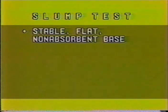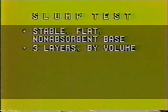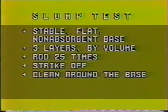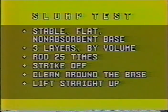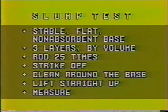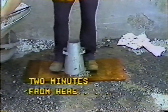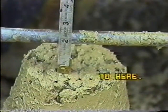And that's the slump test. On a stable, flat, non-absorbent base, fill the cone in 3 layers by volume, not by height. Rod each layer 25 times, spiraling toward the center. Strike off the top layer. Clean around the base of the cone. Lift the cone straight up without twisting or tilting it, and measure from the bottom of the rod to the top of the concrete, directly above the center of the base of the concrete. There's a time limit too. 2.5 minutes between the point where he starts filling the cone to when he measures the slump.